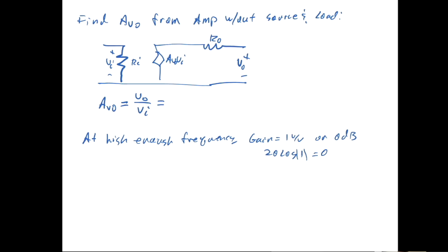Well, in a real system, it's not a short, it's not 0. So the input resistance can be infinite for an MOS transistor, but the output resistance is never 0 for BJTs or MOS transistors or any others. There's always some output resistance, although in the lab, sometimes it appears as if there isn't any. Some transistors are made with an ancient, remarkable technology where it might actually seem that way, but modern transistors are way, way far from it.